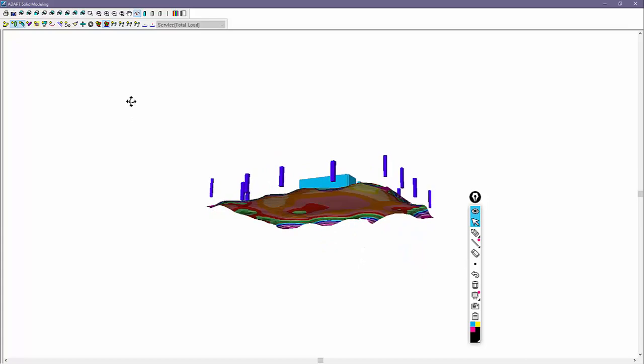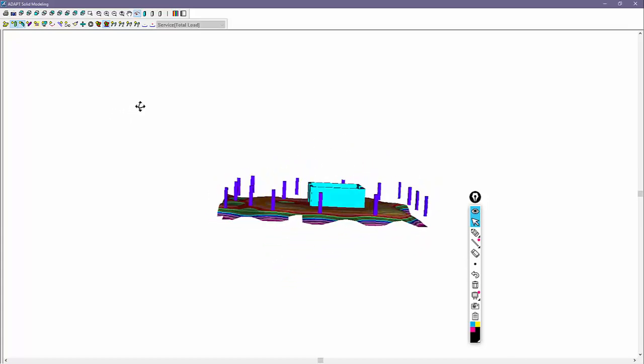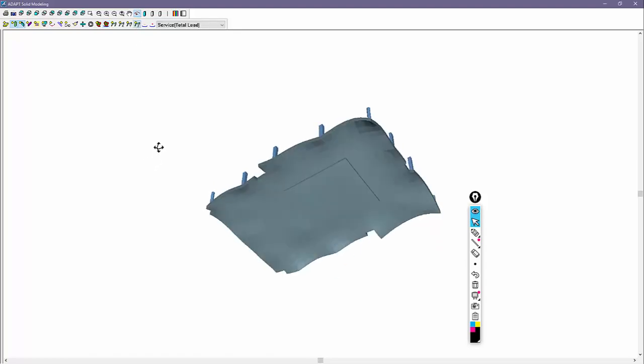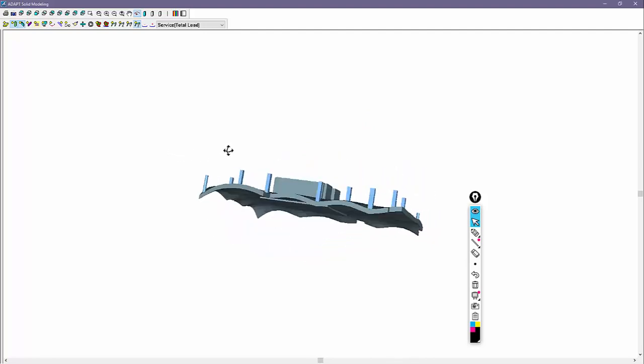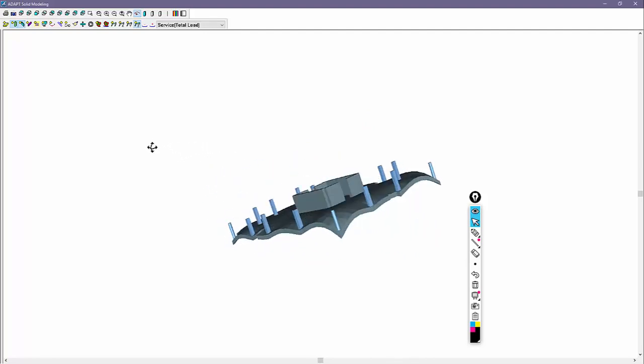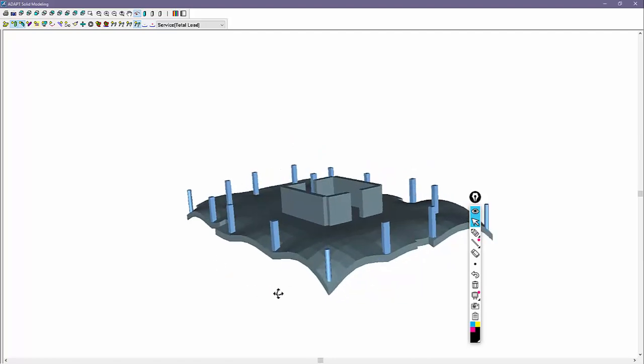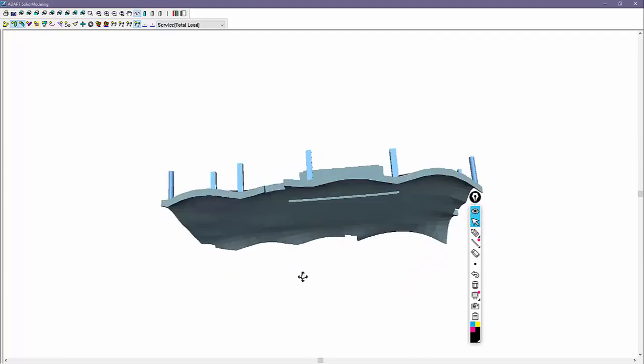Now this warps it just as a 2D kind of folded membrane in this case. I can also extrude the mat by using this option for deformed shape, and this just gives a relative view, I guess, of the deformation in that slab and helps a user just validate the general deformed shape that might be expected under the loading conditions.